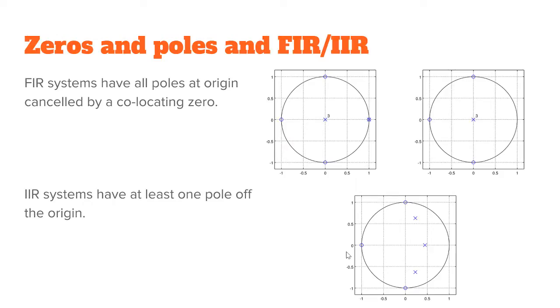I think last time in the classroom we already found out the 4-point running average filter has the zeros here and poles here for this representation, but for the feedback representation we had also one pole here and also a canceling zero at the same spot, meaning that it's still FIR because these cancel out and all the poles are otherwise on the origin.